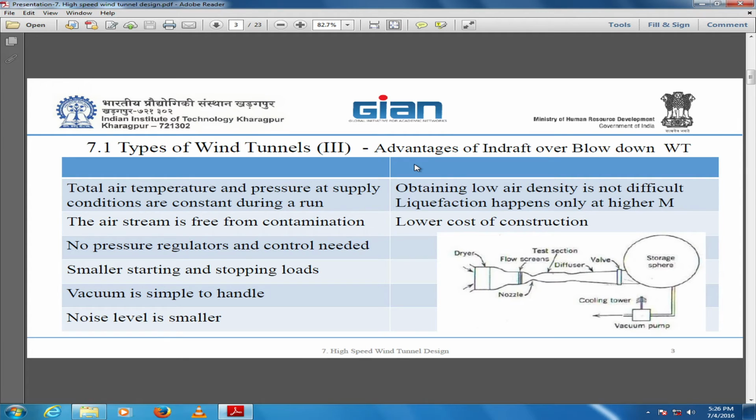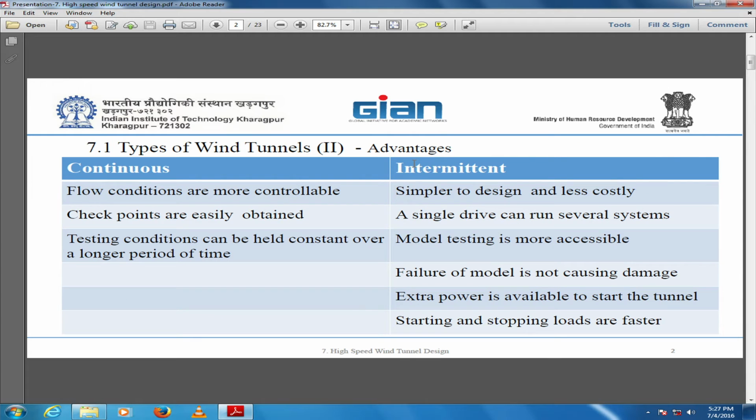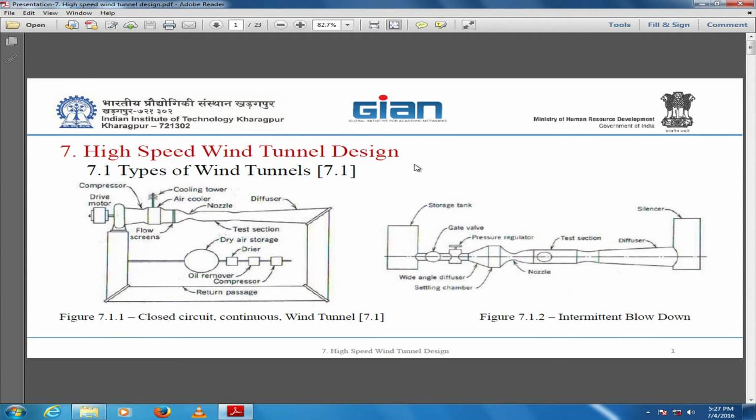On the previous slides, sir, the one before this. We use a divergent duct for a diffuser. In the hypersonic case, that doesn't act as a diffuser, right? It's only a convergent duct that acts as a diffuser for hypersonic conditions, for high speed conditions. Please repeat your question. So for high speed conditions, yes, it is a convergent duct that acts as a diffuser.